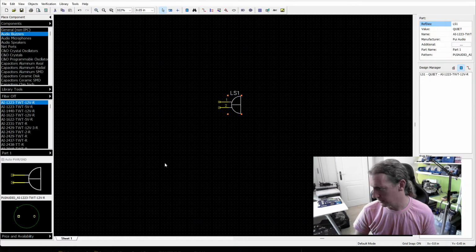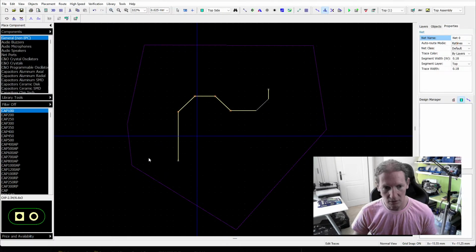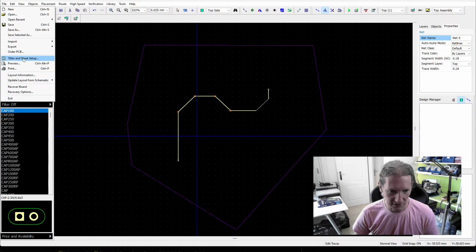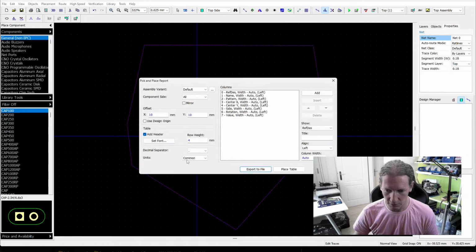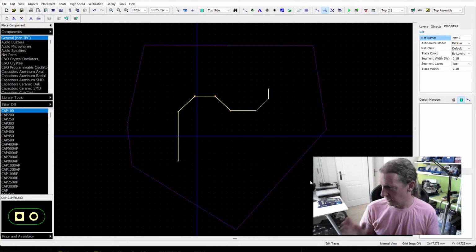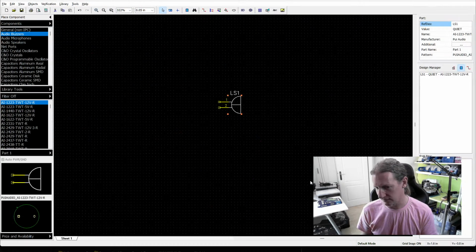Then you've got new pick and place export files from your PCB design side of things. In DipTrace, these are created by doing this, and it gives you a CSV file. But before you do that, you import the updated schematic, and then the pick and place export file will have a different value for the component that you changed.